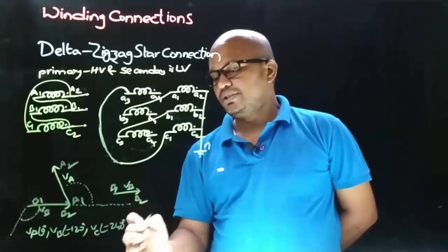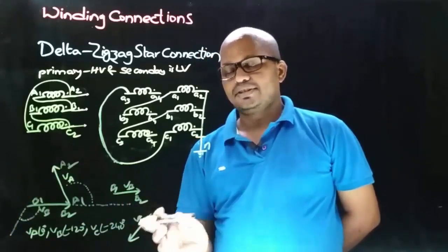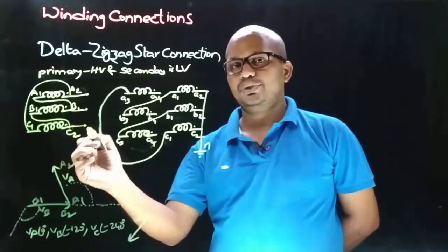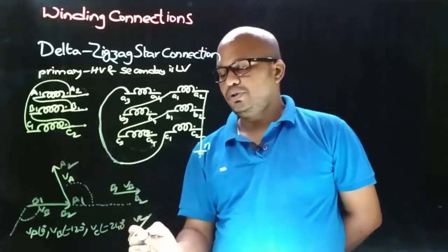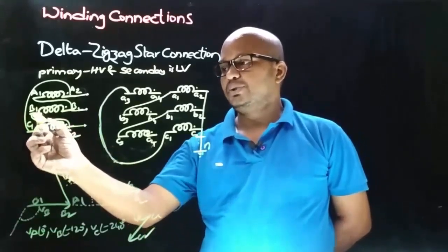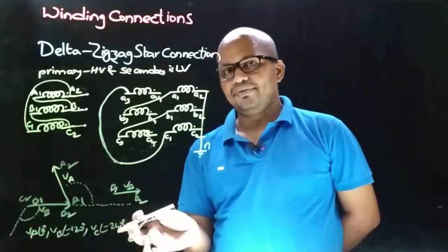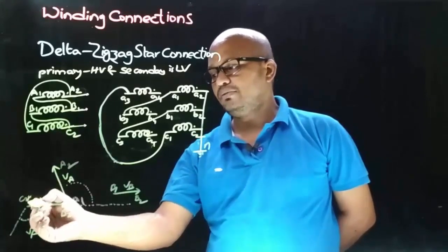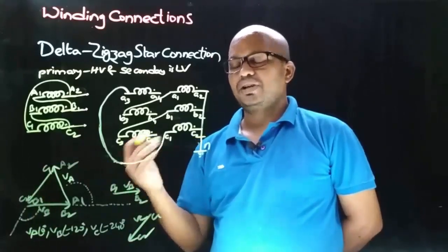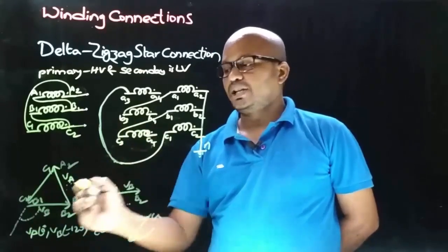So let's consider this as VC phasor, and now let's decide the terminals of this VC phasor, and observe in winding connection that C2 is the connection we took from, therefore arrow will point towards C2 and other end will be C1, and observe in winding connection that to B1 there is C2 connection, so here there must be C2. So place this phasor here such that B1 will have C2 connection, so this is the C1 end.